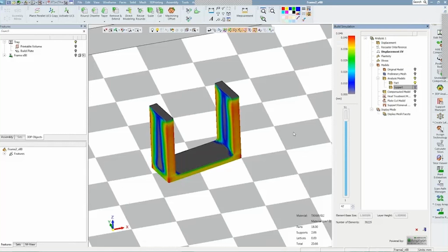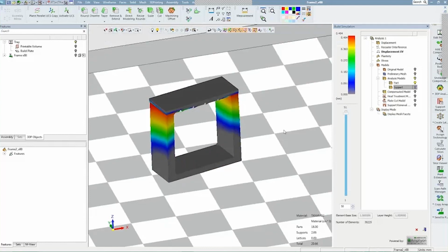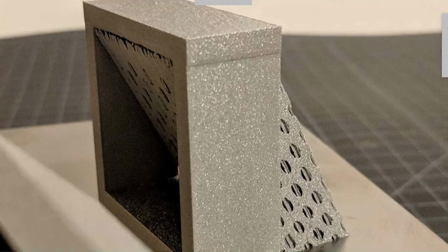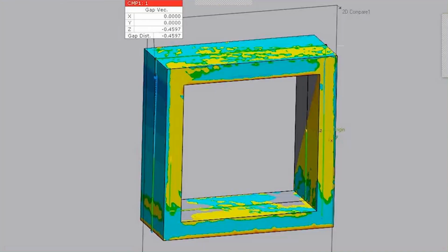So really aren't seeing too much until we get to that connection. And you can see it jumps right back up to 450 microns. So that's a pretty significant deformation. But let's look at what that looks like on a part. So here it's immediately obvious that you have a line here. A lot of people think it's a positive sometimes, but it's really that negative is your deformation. You can also see on the top left you have some curling.